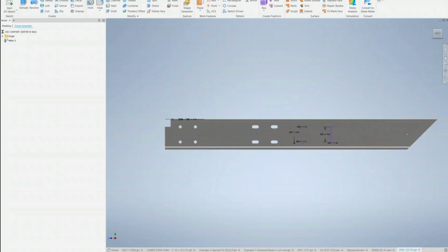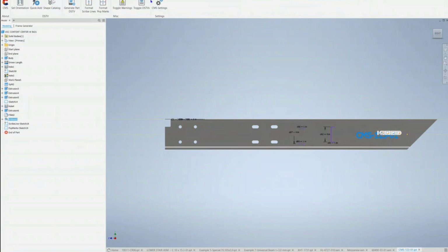If you take a look over here, in the modeling tree, one of the things I see is an embossing feature. So I expect to see an SI block coming from the embossing on the front web. At the same time, I have sketches and unused sketches. As I mentioned before, I can bring any sketch line as a scribe line, given that the scribe line has not been consumed.